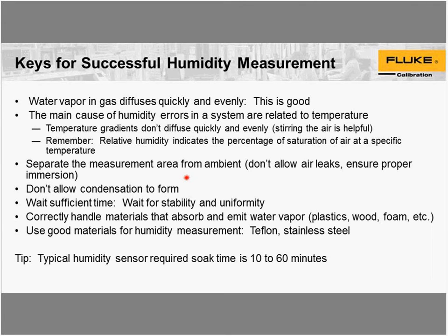Don't allow condensation to form. I think we've already talked about this, so keep an eye on dew point. Be careful, and recognize that the temperature and humidity inside the chamber may not reach a dew point, but the temperature outside the chamber could cause the air to quickly condense if they start interacting, and so you can get condensation, like on the door where the chamber and ambient temperature meet.